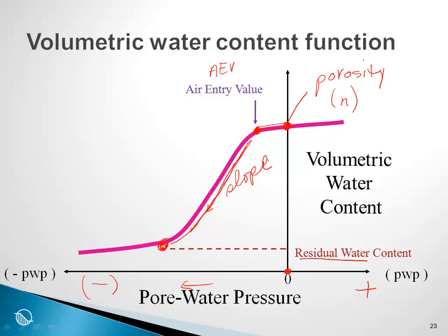We will talk about this more at the end of session 1. So for very granular materials, the slope might be very steep. For clay soils, it might be very flat. So the slope is related to the soil particle distribution and the size of the distribution of the voids.